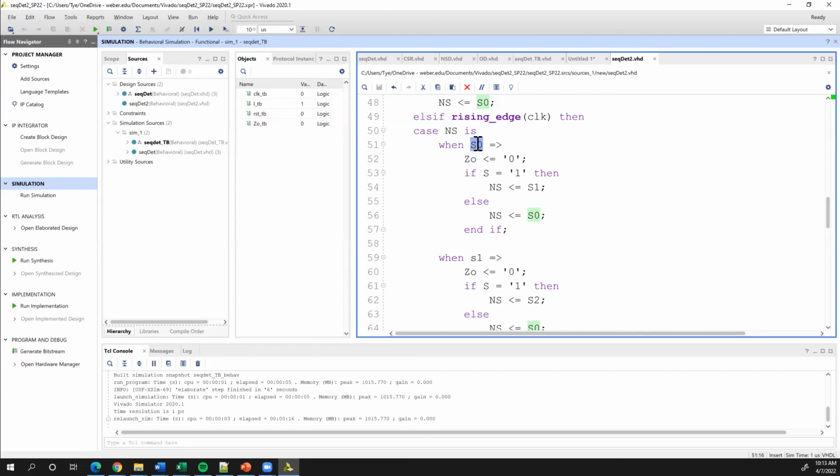Okay. And so in the case of the garage door opener, one of the states is ready to go down, right? We're going to be sitting at the top. We want to be ready to go down. I'm going to push the button. It's going to start going down. So my case statement is when ready to go down, if button is 1, then move to state going down. If I am in state going down and the sensor is tripped, then go to state going up. Right? Most of the time they start going back up if you trigger the sensor, right? It's literally as simple as, what do I do in the state based on my inputs? If this, then that. If this, then that. This makes designing state machines of tremendous complexity very simple, as long as we can think logically.